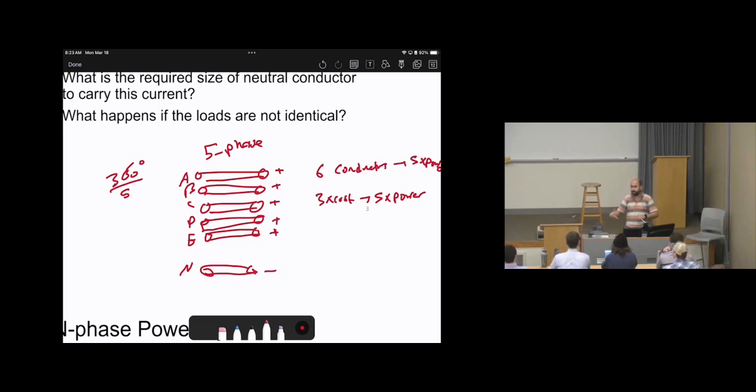If we have five phases, this means we will have a larger power tower size. If this tower is going to be larger and larger, this means more overhead cost in building that tower. You need more steel, you need more concrete in the bases, and these towers need a large thickness or a large capability of handling these loads.